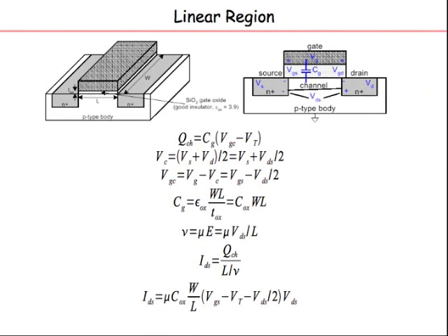So here what we have is a perspective view of a transistor. Remember, in the previous pictures we were just looking at this face. We had just taken a slice through the transistor, where we had the source and the drain region, the channel and the oxide. The distance between the source and drain is a very important parameter. It's called the channel length, the length of traversal of the carriers. Now this depth out here is the width. So this is how the transistor looks in perspective. This whole thing is the gate region. You have the width, you have the length.